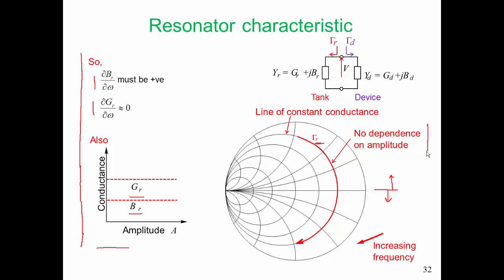When we're designing a fixed frequency oscillator, we can deal with a resonator which is using ideal components, or near ideal components, in the resonator network. We don't have to use a reverse bias diode, but with a VCO we must. So with a fixed resonator network, we have more degrees of freedom in the design of our oscillator. Since we're dealing with a VCO with a Varactor diode, there will be finite conductance.